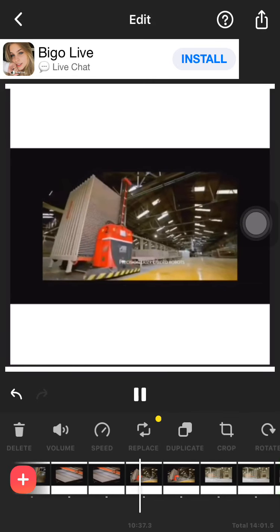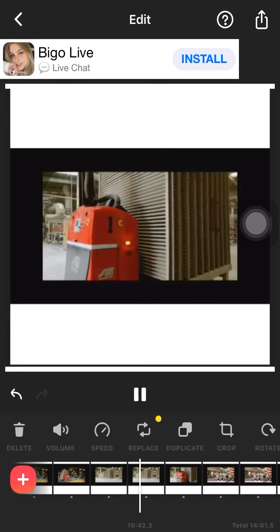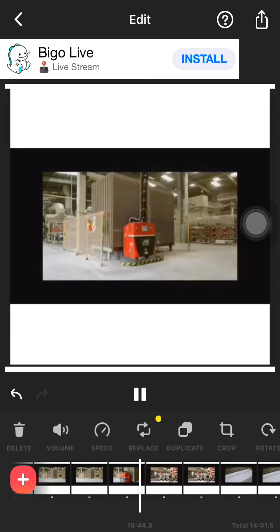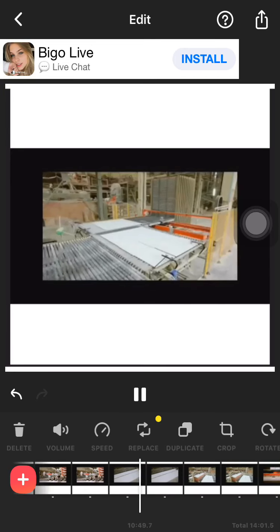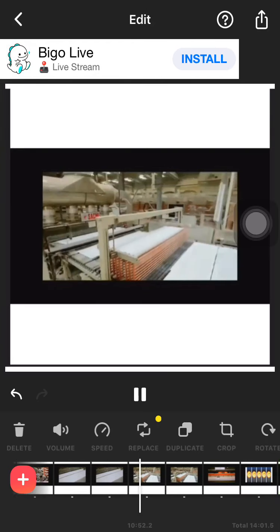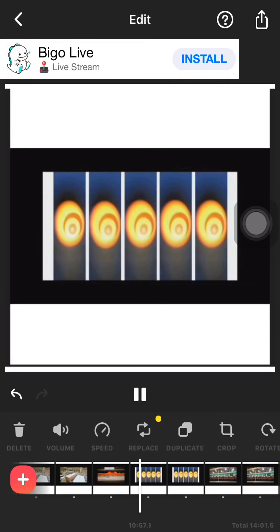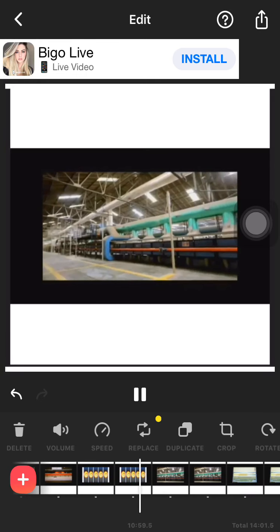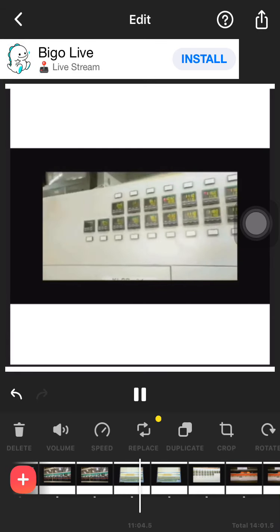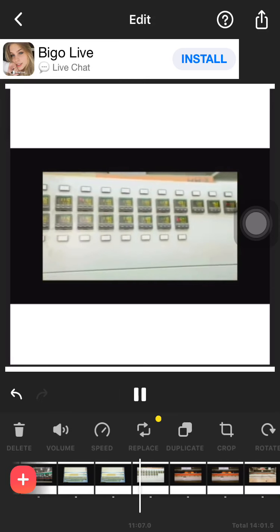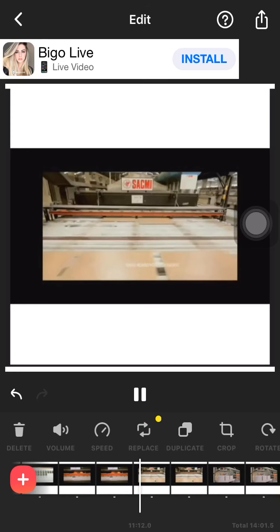Special laser-guided robots stack and order the tiles and take them to the central kiln facility, all without any human intervention. The kiln processes raw tiles and makes them strong, durable and beautiful. Tiles are heated up to 1200 degrees Celsius in 5 different temperature zones, emerging ready at the end of the 145-meter-long journey. From the length of the kiln to the fine temperature control, everything is calculated to impart durable strength and rock-like toughness to the tile.